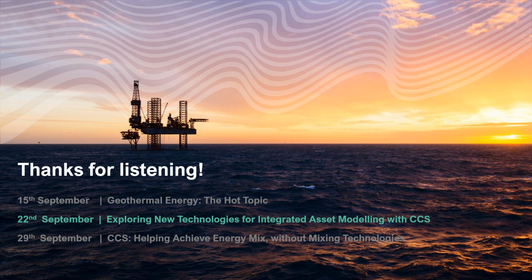Yes, obviously the wellbore is attached to the reservoir and also to the surface network, so you can plot the temperature and pressure profiles within the well section, like we did on the video briefly. In the initial part of the wellbore modeling, you can also define a temperature gradient. So you have the static side, your input, and you also have the dynamic side about how the temperature and pressures are changing down the wellbore, which can be visualized in your reservoir.